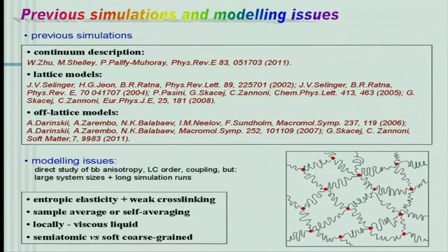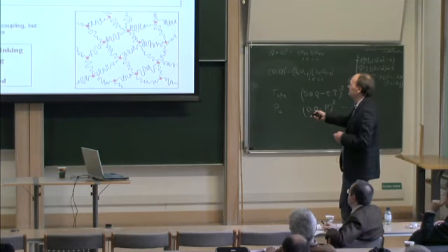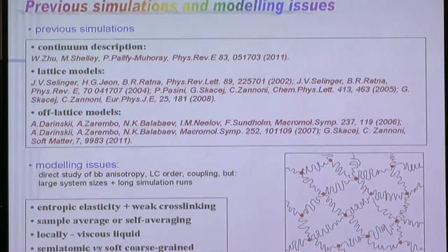So this is the network of the polymer network, and to have the entropic elasticity of the network, we need a large conformational space of the chains between the crosslinks. So this already means that the chains should be sufficiently long. Also, we need a weakly crosslinked system. Otherwise, we will end up with a thermoset and other solid materials. So that means that chains should be long and the crosslinks should not be so many. So that blows up the required size of the system.